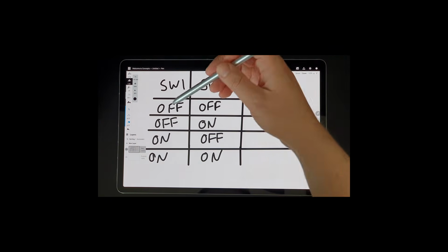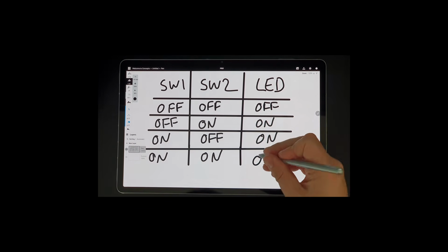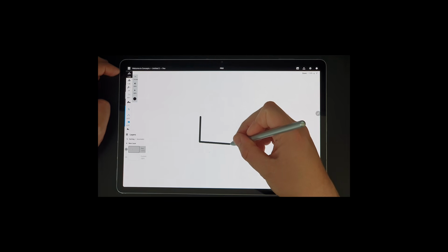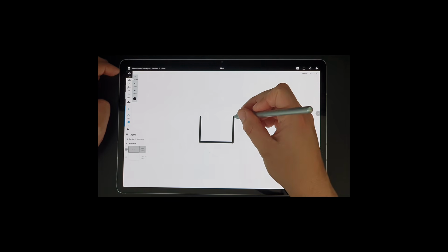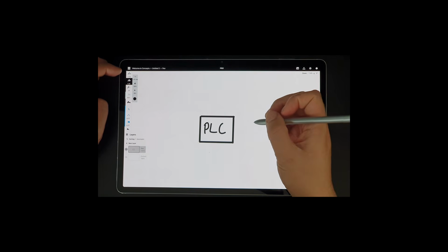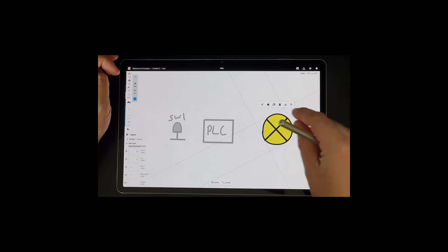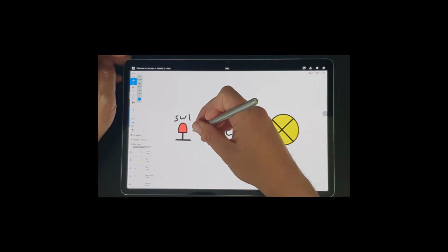On the table, you can see the logic we just discussed, where either input being on will cause the output to be on. Anytime we want to alter our system logic, we would have to physically rewire the circuits. In complicated systems with numerous inputs and outputs, this can be tricky and time consuming. So we developed programmable logic solvers to do the work for us.